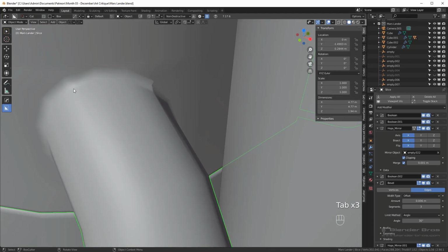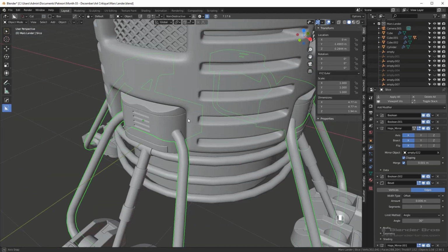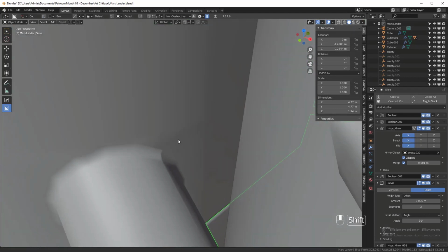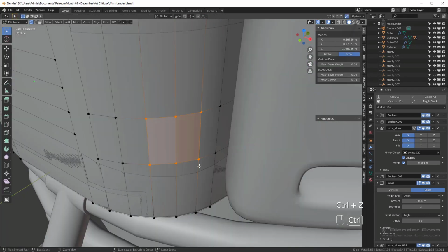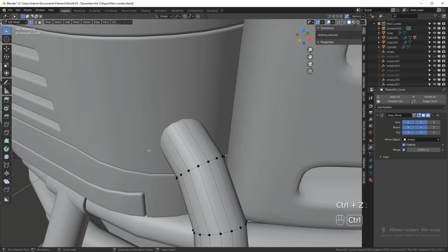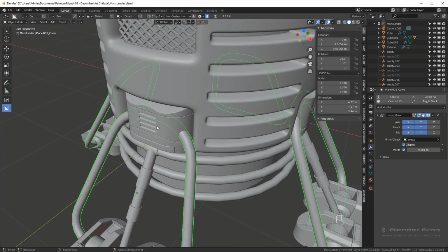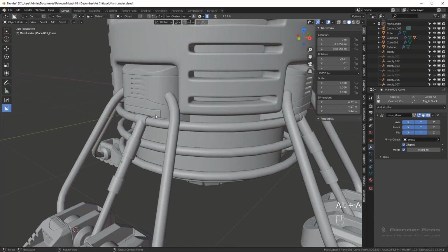The only bad shading areas are around here. So from a distance, not really a big deal, but I would try your best to get some nice shading in there. So yeah, a union's probably your best bet unless you want to get in and change the topology and make a circular cutout for it. These are the types of things you always want to plan out beforehand, because then when you try to go back and fix it, then you have to deal with bad shading, artifacts, mesh cleanup, whatever it may be.